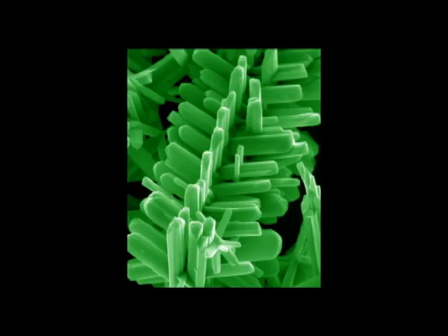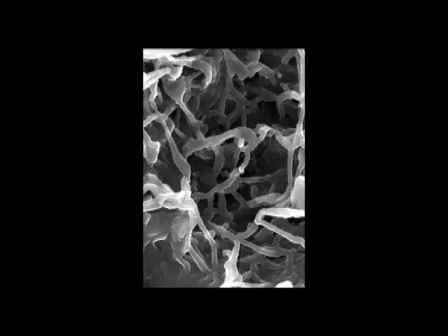Although these superlattices are promising, they are difficult and costly to produce. Nanocomposites possibly represent an ultimate solution. Nanoparticles of thermoelectric materials can be made via cheap processes such as sol-gel, ball milling, and solid-state reactions. They can then be compressed as macroscopic ingots with nano-sized grains. The grain boundaries scatter phonons and give impressive figures of merit, close to 3.0.